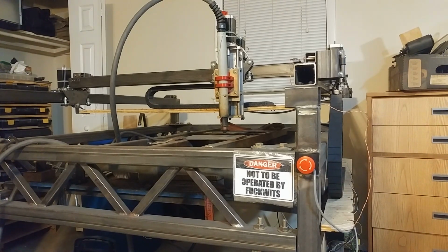Another feature of this component is that, while it calculates the offset you've applied during that entire torch cut move, when the torch turns off, it tries to roll the offset into your next intended Z move. So you do a G0 or a G1 in the Z axis direction, and it takes part of that offset and rolls it into the move to get rid of it, without the program even knowing it's happening. And again, I found some edge cases in that logic where it doesn't do exactly what it seemed to intend.